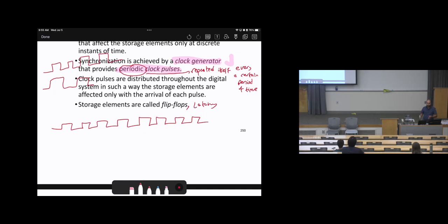After creating the latches and flip-flops, each latch or flip-flop is associated with 1 bit. To create 1 byte, for example, we need 8 latches or 8 flip-flops. This group of flip-flops or group of latches, used to store 1 byte, is called a register.